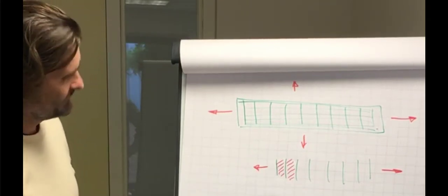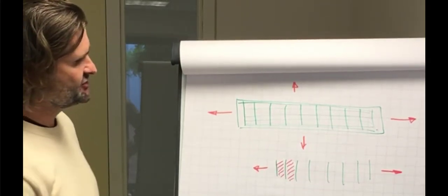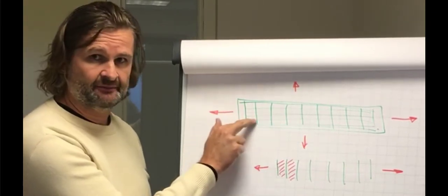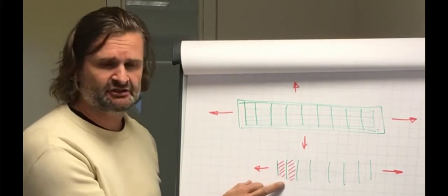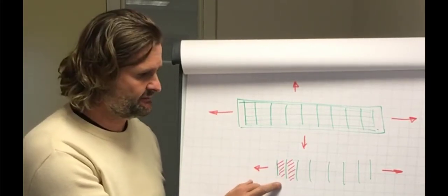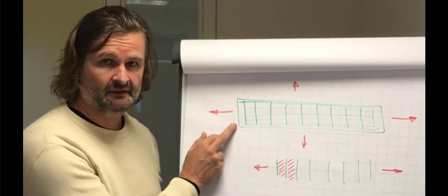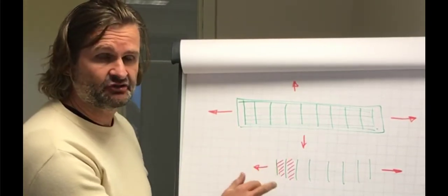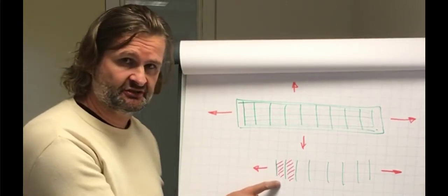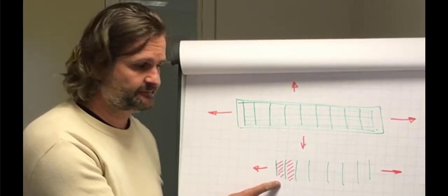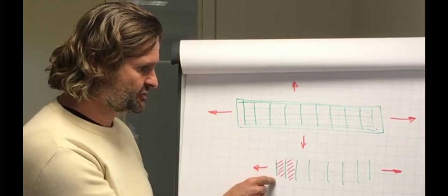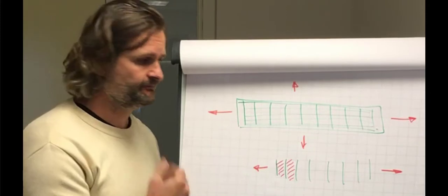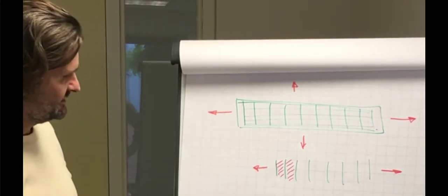Now that means that the deformation that is caused by the load and by the flexibility of the horizontal fibers determines the deformation of this layer as well. This layer simply has to go along with the other one. And that means that not the load or the stress in this layer determines when it's microcracked, but the deformation causes the moment when it microcracks. And the deformation is caused by the modulus and the stress in the fibers horizontally. So there you have it, actually.